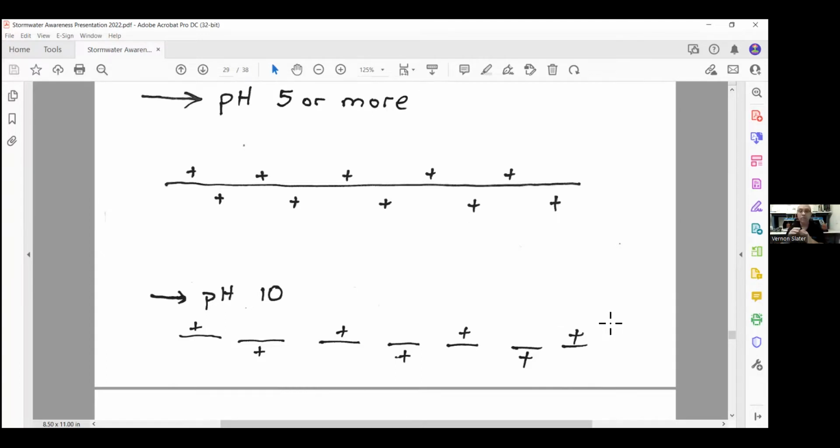Which, Vern, I think leads into a follow-up question about what was being asked earlier, and I believe you just illustrated why that's the case. The question says, if ATS works not so well on some CIDH projects, and remember he was talking about high pH, which you're just illustrating there, I'm guessing because of high molecular weight, drilling fluid is difficult to remove and thus needs special filter media. What I'm hearing from what you just said is maybe it just needs pH adjustment. It's possible pH adjustment will get it, but what we have found when dealing with CIDH is usually there is another particular material that breaks down the CIDH polymer better than chitosan will. Oh, okay. All right, and I'm sure you're going to be talking a little bit about what happens when you go with different medias and what the permit requires. All right.